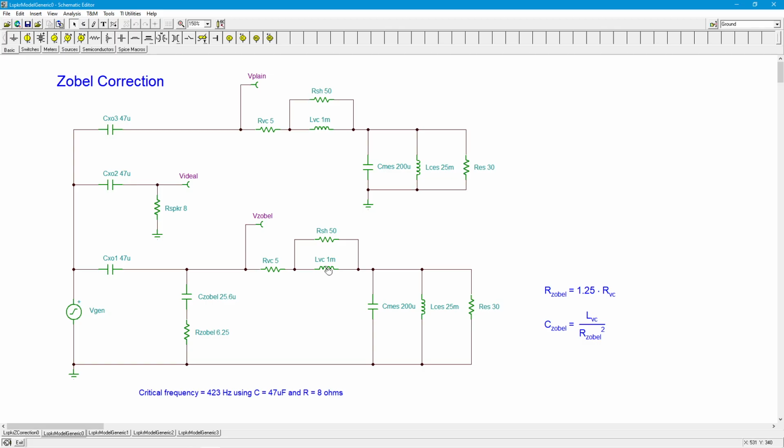One is a positive phase angle, one is a negative phase angle. If I set them up correctly, they can cancel perfectly. I need the resistance in here because if I don't have the resistance, and I just put the cap over here, that's all I had, then the impedance would keep on falling as the frequency went up higher and higher, and we'd basically short out the power amplifier at really high frequencies, and we clearly don't want to do that.